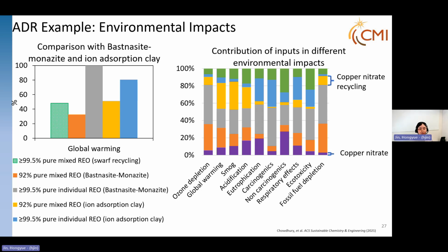So we looked into the impact of our product with this comparison and found that ADR could have lower environmental impact, especially if we can reuse the entire rare earth without separation. The major distinction between the lower bound and upper bound is separation into individual elements, as rare earth in the swarf already contains the rare earth proportion for the NdFeB magnet application.